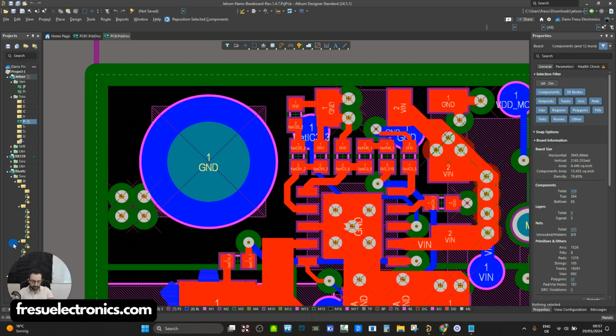One of the ways that we're going to achieve that is by using the decoupling capacitor. By using the decoupling capacitor, we are bringing a source of energy as close as possible to the IC. And this means that the inductance between the decoupling capacitors and the IC can also be reduced, because the decoupling capacitor can be placed very close to the IC, so the inductance of the traces can be reduced.